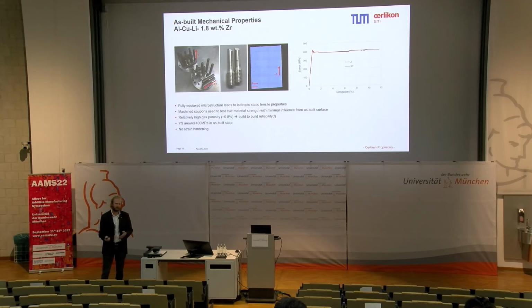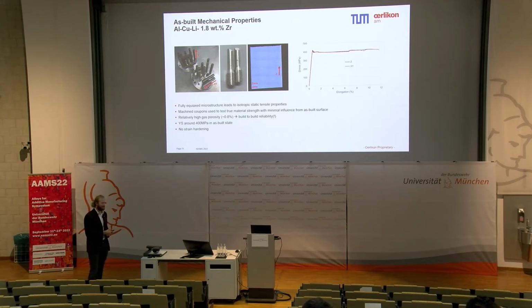After cutting a witness cube and some of the coupons themselves after testing, we observed much lower density than what we've previously seen. That's an important thing to point out here. This is an example of how build-to-build reliability ought to be tested more frequently.